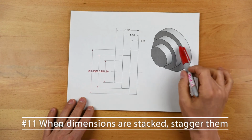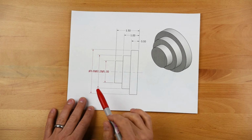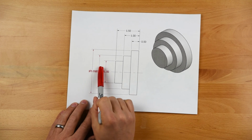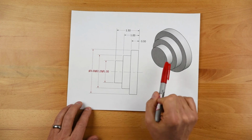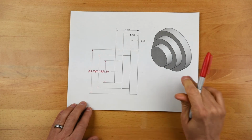A little different one. We have this shaft of concentric circles, dimensions, and what you'll see here in red is that although it seems like it would be a good idea to line all these dimensions up, in general, when we have sequential dimensions like this and we're dealing with a shaft and diameter, we really don't want that to happen.